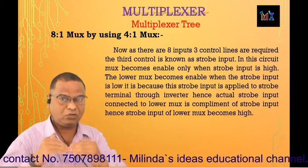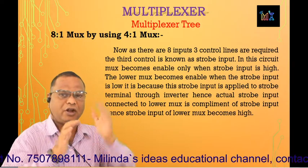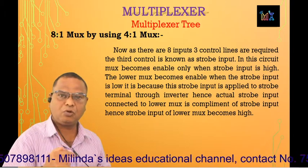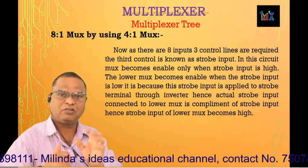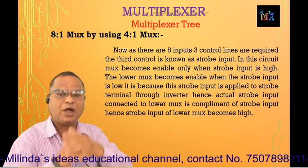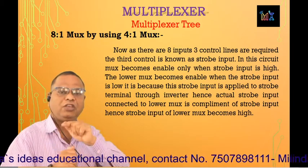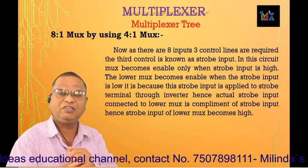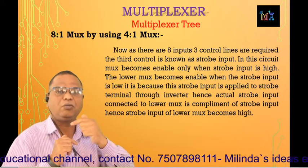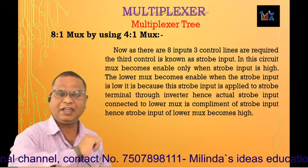Below this, up to 0 1 1, the lower mux, that is M1, is in enable mode. Why is it in enable mode? Because the strobe input of this mux becomes high, since the low input at the S2 terminal is converted to a high input by the NOT gate, the inverter. So up to 0 1 1 the lower mux, M1, is in enable mode, and the data connected to that mux, from D0 to D3, is selected as per the input signals S1 and S0.